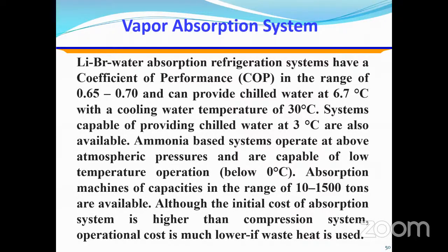Systems capable of providing chilled water at 3 degrees centigrade are also available. Ammonia-based systems operate at above atmospheric pressure and are capable of low temperature operation below 0 degrees C. Machines with capacities in the range of 10 to 1,500 tons are available.